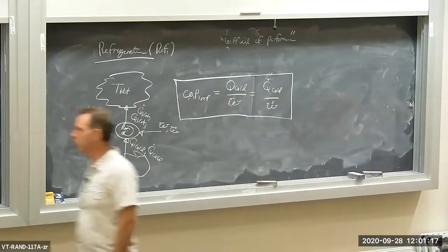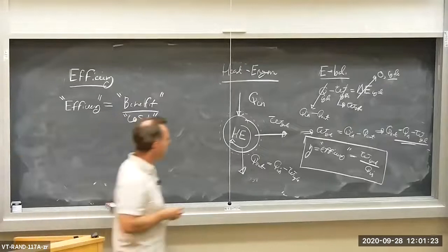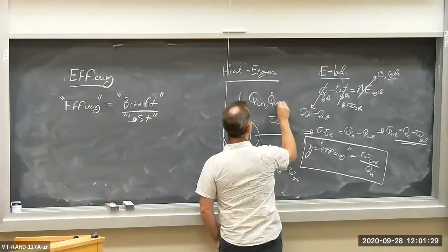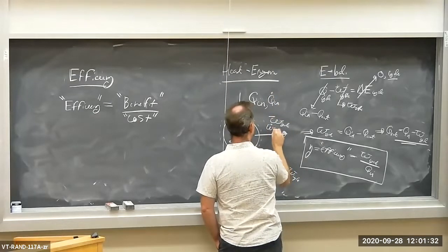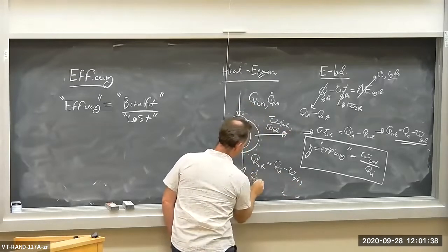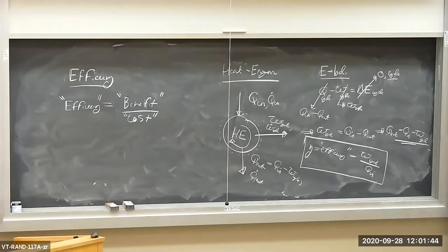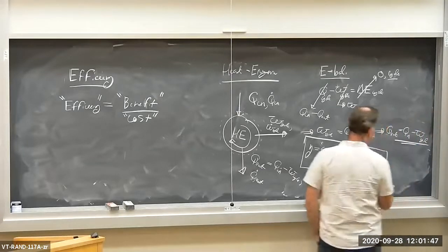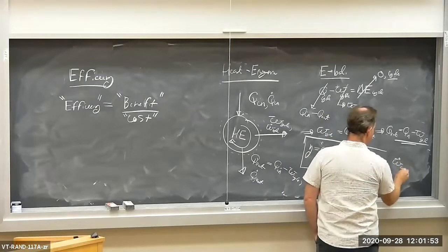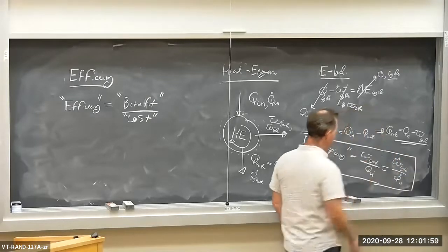And we can also do this for a heat engine. Let's go back and clean up our picture for a heat engine. This could be a continuously running device. So I have Q dot in, I have W dot cycle, and I have Q dot out. So I could rewrite this expression for efficiency for a continuously running device. I can add in one more expression, W dot cycle over Q dot in. I could do this, and I'm going to, okay?